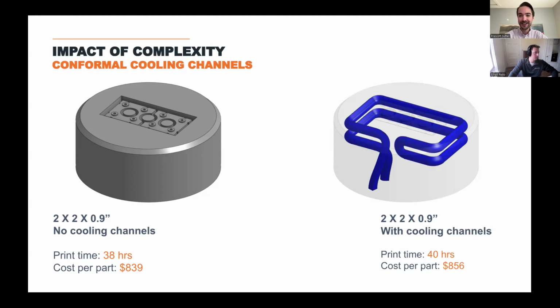Again, it doesn't come for free, but the advantages of leveraging 3D printing and the capabilities you have in the way of design flexibility to create conformal cooling, in this example here, could give you tremendous advantages in the way of cycle time and throughput when you're going to mold these parts. So my statement holds true, not for free, but it's a discount you get here.